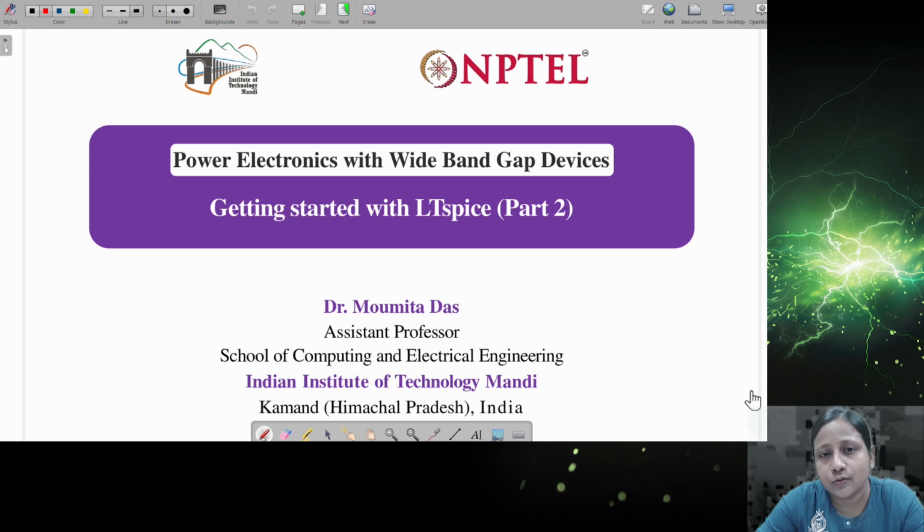It can be a GaN switch or silicon carbide, since we are discussing wide bandgap devices, and use it in simulation to see the performance of the converter, which will be close to the practical converter operation. That is why we have chosen this LTspice simulation.